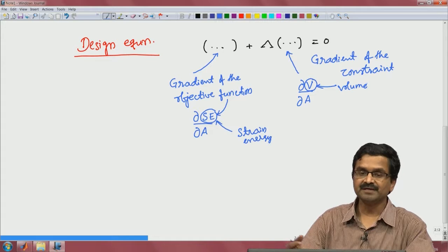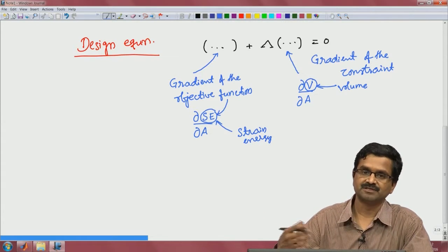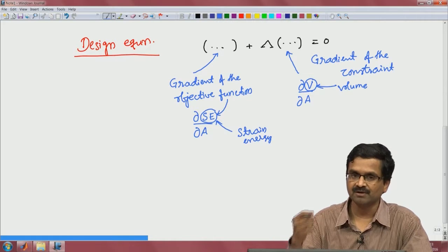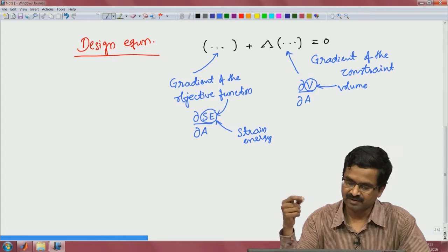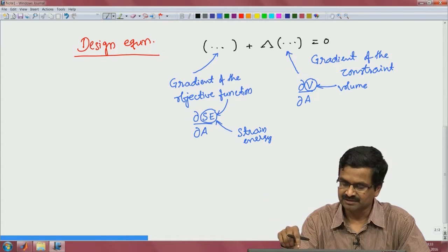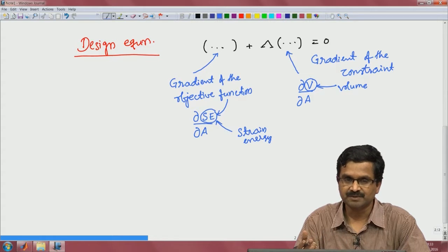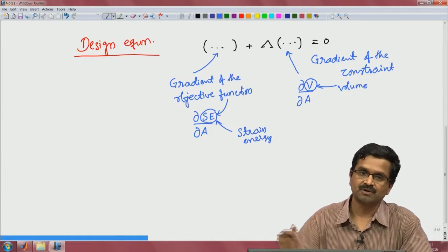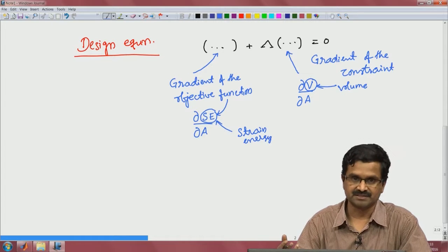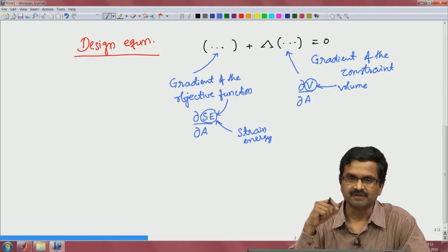Okay. And from here, by knowing that in this particular problem lambda is equal to u, that is, the adjoint variable or Lagrange multiplier lambda of x is the same as u of x, we got a design equation which became simple enough to interpret, saying that strain should be constant everywhere, u prime equal to constant everywhere. So, basically that is how we solved for A of x in this problem. Again substituting that back into the equilibrium equation.